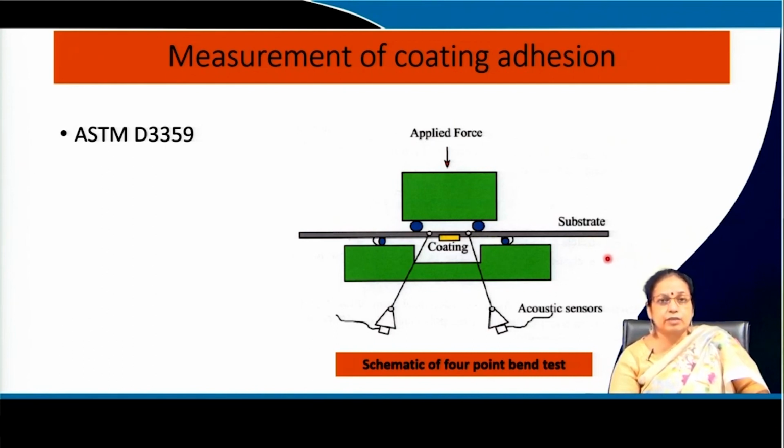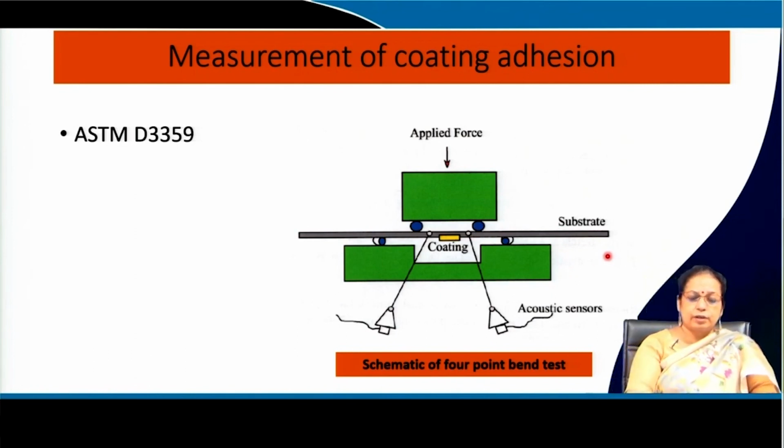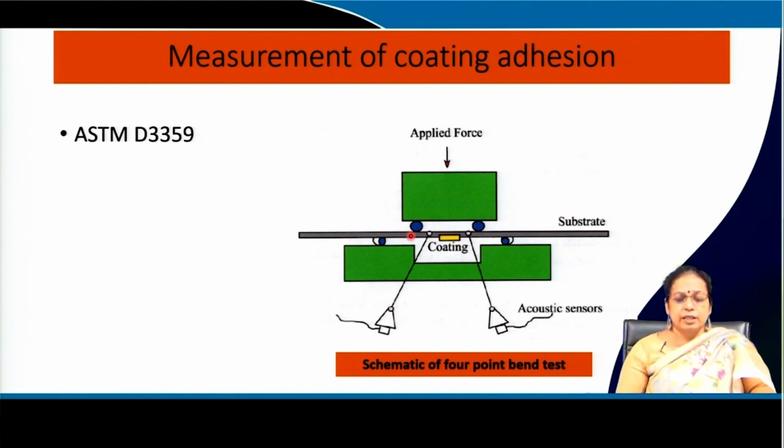those coating techniques, if you see the coating deposition, you will find that the coating actually gets deposited on the surface, but there is minimum interaction of the coating with the substrate. So, in that case, because of very less interaction, you can say that the substrate-coating interface is very weak. So, bond strength is one important parameter which needs to be specified whenever you talk about coating. Different coating techniques actually offer different bond strength.